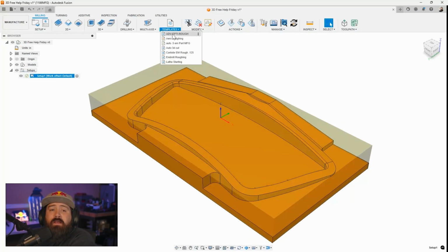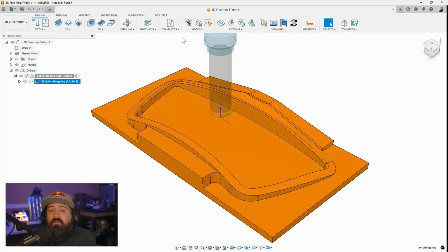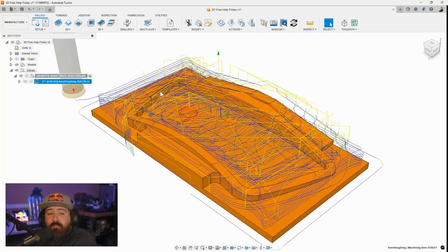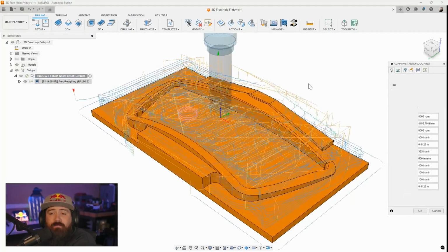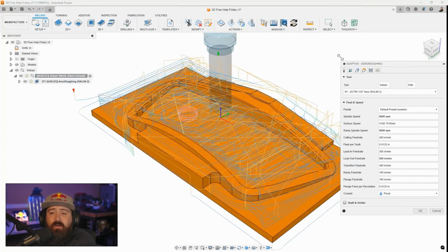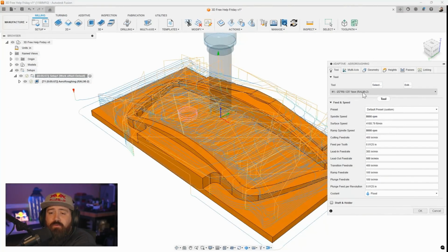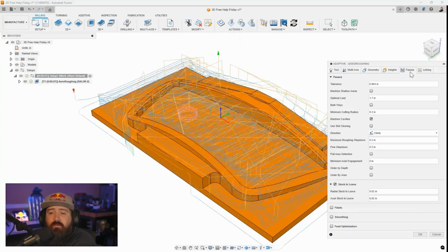While we're going through this, I'm going to add an arrow roughing toolpath. So this, for me, is a toolpath that is using a bigger kind of face mill. So this is using a 2-inch face mill. And then for my passes here, the reason I've made this a template is because this isn't a traditional way that I'd use the adaptive. I have a pretty wide step over here, I don't know, 70-80% of the width of the cutter, and then I'm taking a small step down.